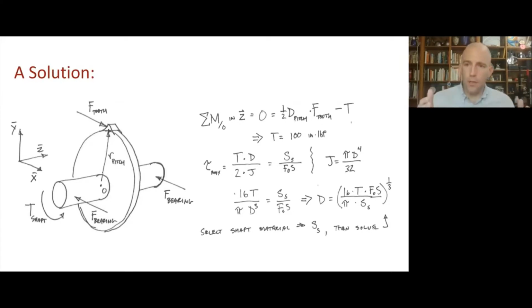And this is also in the topic reading, so we did some of this math for you already, and maybe you just went to that equation straight away. So this is going to give us a way to solve for the diameter that exactly hits our desired factor of safety, given a material and given that we already know what torque it needs to take.